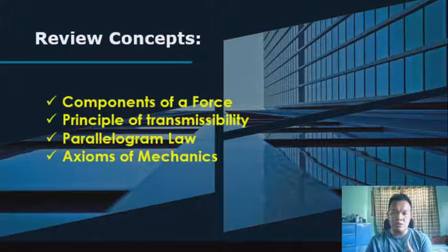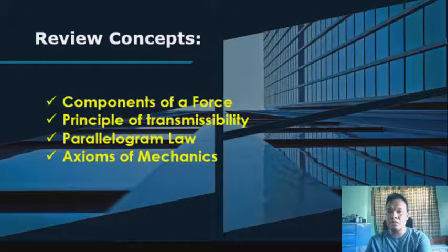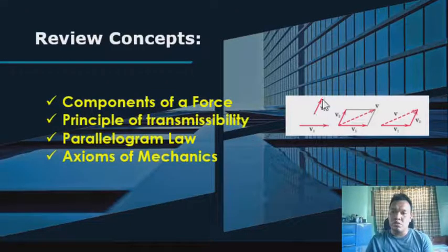Na-discuss ko sa inyo na si force, meron tayong vertical and horizontal component, no? Then, we also discussed principle of transmissibility, which means na yung force is pwede nating i-transfer into another location as long as dadaan siya dun sa line of action nung force na yon, no? Then si parallelogram law, so kumbaga itong forces na 'to at forces na 'to is kung gagawin nating isa, kailangan lang natin bumuo ng parallel dun sa kabilang force at parallel dito sa kabilang force, and the diagonal will be the resulting force na 'pag pinag-add natin yung dalawang force or velocity na 'yan, no?